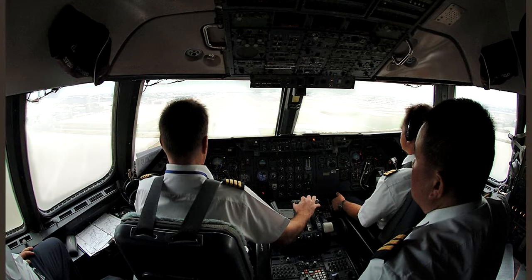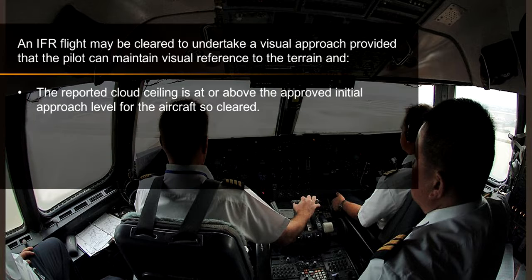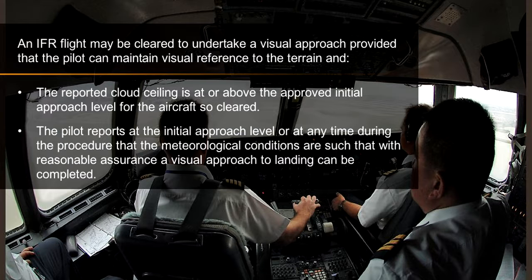An IFR flight may be cleared to undertake a visual approach provided that the pilot can maintain visual reference to the terrain and the reported cloud ceiling is at or above the approved initial approach level for the aircraft so cleared, or the pilot reports at the initial approach level or at any time during the procedure that the meteorological conditions are such that with reasonable assurance a visual approach to landing can be completed.